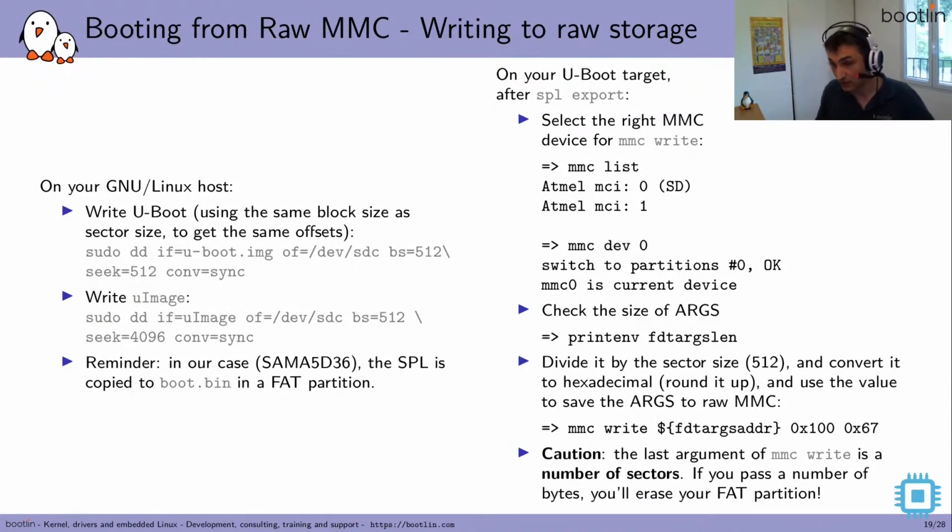So be careful here. mmc write really takes a number of sectors as the last argument. If, as I did, you pass a number of bytes, you'll erase your FAT partition. So that's a disaster. Don't forget that.